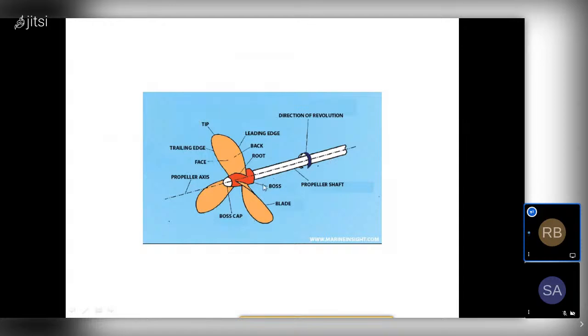Okay, so as I told, in this case we have three blades. These blades of a propeller act as a rotating wing, and they produce a force through the application of Newton's third law, generating a pressure difference between the forward and rearward surface of the aerofoil shaped blades.